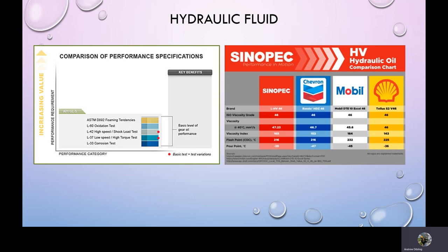Now, I did work in a mine in northern Alberta that had a lot of hydraulic equipment, and the hydraulic systems in there, if they were kaput or no good, we would bring them back into the shop. There's no way that you would try and pour oil or try and run a system from a cold start at minus 30. The temperatures that we would experience in northern Alberta would be very much around that minus 40 mark in January and February. So anytime we were using oil, it would be pre-warmed. We would bring it out of a nice warm shed to put it into the system.